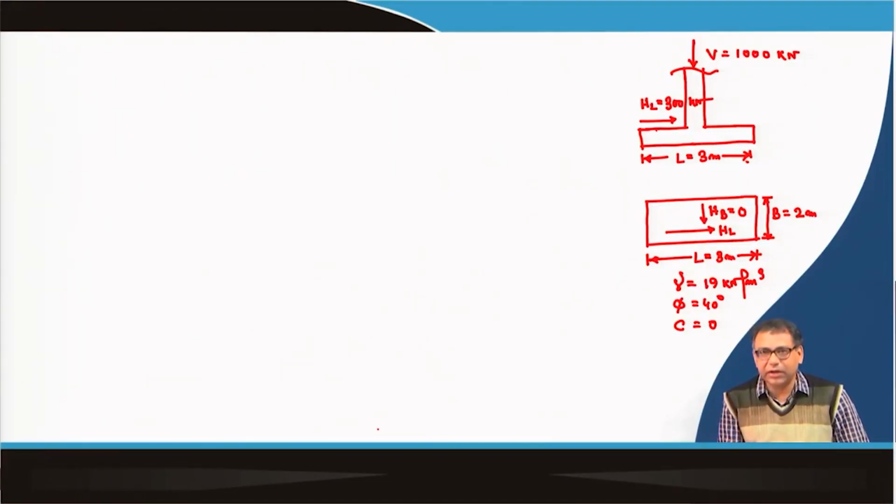That phi value we can use for this case, but if my loading is for a strip footing, I cannot directly use that phi value, because strip footing is a plane strain condition, and when you determine the triaxial phi, that is not under plane strain condition.